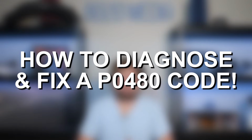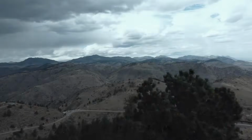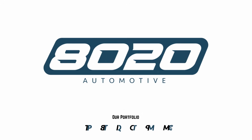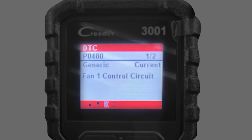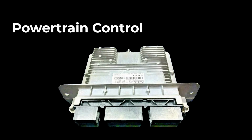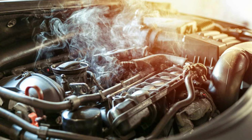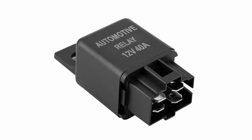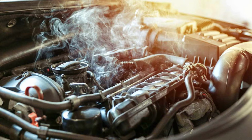Fault code P0480, symptoms, causes, and diagnostics. P0480 is triggered when the PCM, or the powertrain control module, detects an issue with the electric cooling fan or its control circuit. When the engine's coolant temperature reaches a certain number, that should trigger the fan relay to actually turn on the electric cooling fan to provide that additional cooling to the engine.